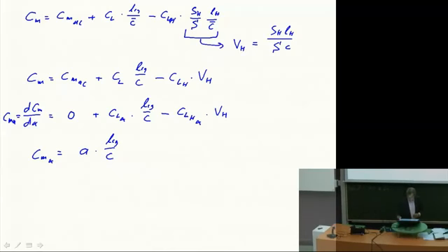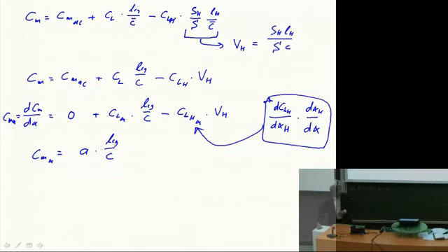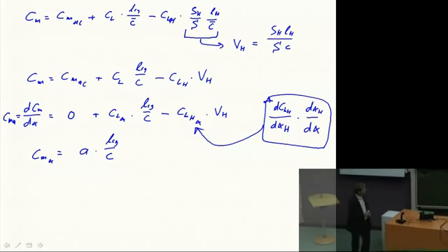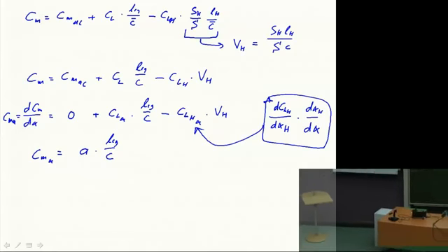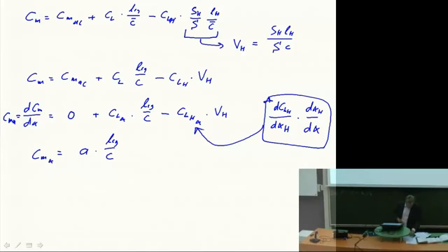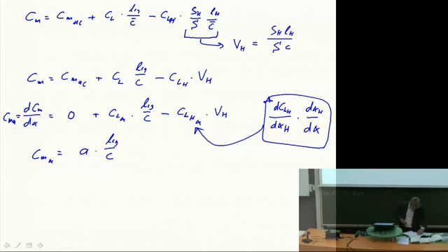If we then multiply this by the change of the local angle of attack as a result of the total angle of attack, you can see that all of this is the same as the one that we're looking for here. Now you see why we calculated this in advance. Because this, apparently, we can just get out of the book, a property of the airfoil, and this we have calculated two slides ago. It's called A for the tail, for instance. What letter did I use in the handout? T or H, or both are used. T, I think, for tail.